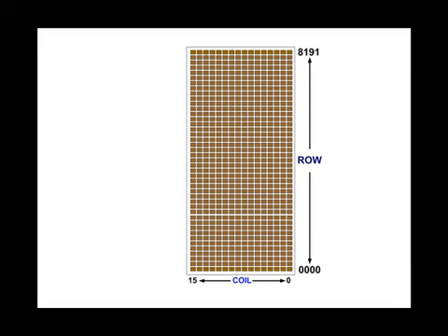Let's take a closer look at one element from this array of relays. Each element of this array has a coil that is on or off, 1 or 0. If we want to allow current to flow in another circuit, if a particular relay coil is on, we use a normally open contact, and if we want to allow current to flow in another circuit if a particular relay is off, we use a normally closed contact.